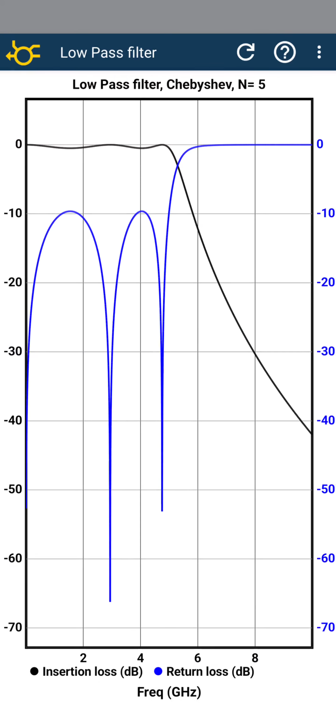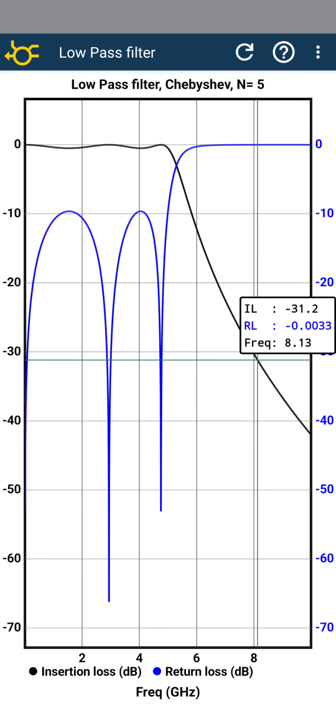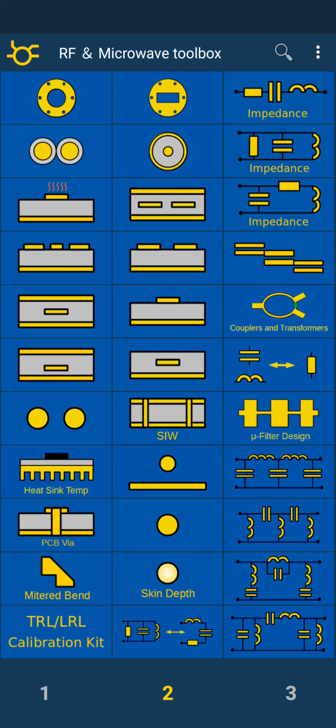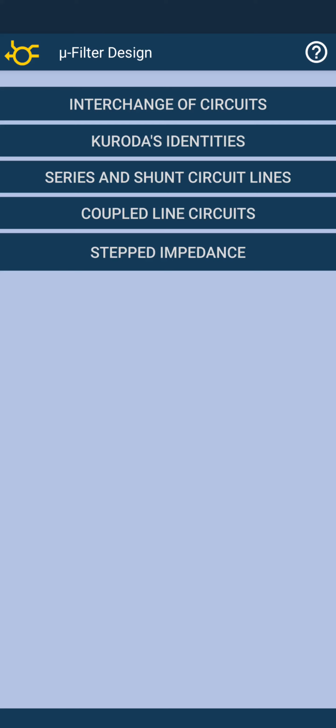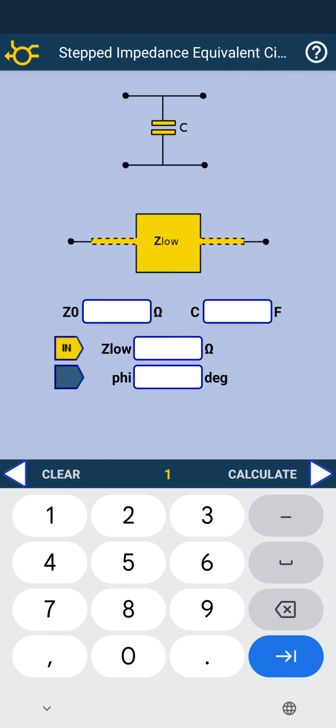First, select the LC values option to calculate the inductor values, then select option G values to calculate the normalized values. Next step is to transform the capacitors to its transmission line equivalent using the stepped impedance tool. For the capacitor transformation, we choose an impedance of 20 ohms.